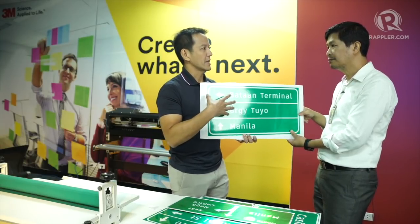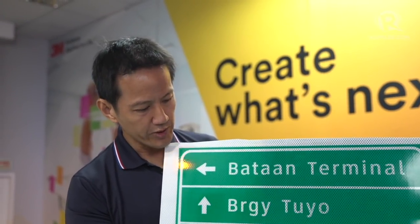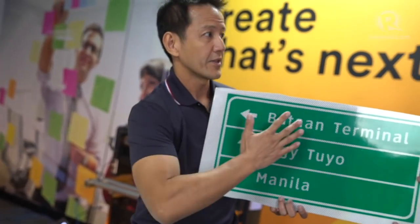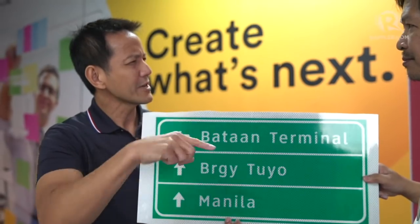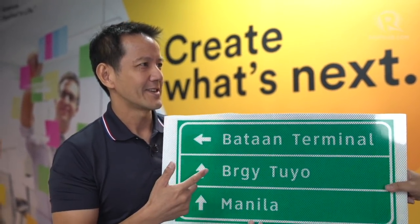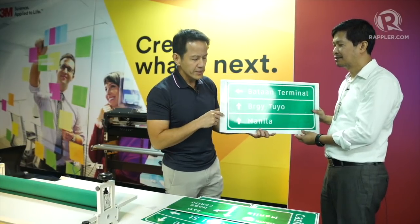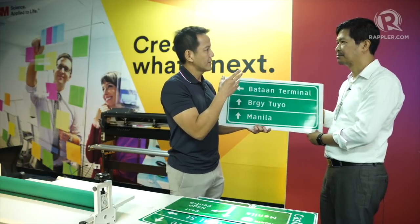So to a great extent, the size of the sign also depends on the actual words. Yes. So if these are short words like Manila or Bataan, then you can adjust the size of the sign. Yes. But if it's a little longer, like Bataan Terminal, then you should adjust the size of the sign to fit the word. Right. Because it seems like the other way around. They fit the word to fit the size of the sign. That has to change. Okay, so it's really the words that determine, to a certain extent, the size of a sign. Yes. But you're also telling me, John, when we're talking about the size of the sign, it also depends on the speed of the road.